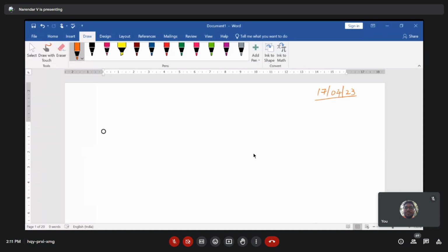What we discussed in the last class was that the RD value, that is the load resistance that you're going to connect, should be less than twice (VDD minus VCM plus VTH) divided by ISS. This was a formula that we arrived at considering a differential amplifier, where RD is limited by this expression.